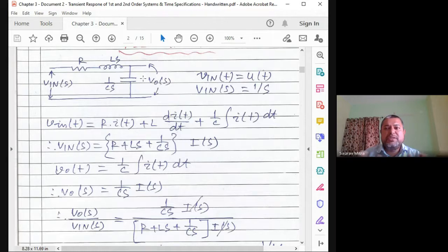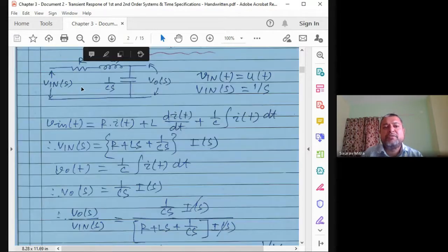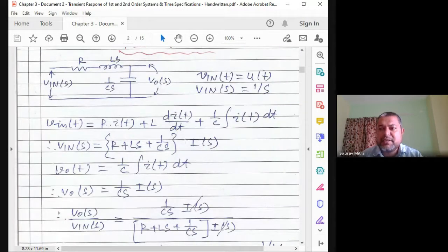So you have to stretch the time axis while plotting it, and find that the output is at steady state. Steady state means the output is not showing any kind of variation or undulation. So first you have to let the output stabilize at a certain level. Then you find the difference between input and output. Then you will be able to comment on the steady state error. So we'll find all that.